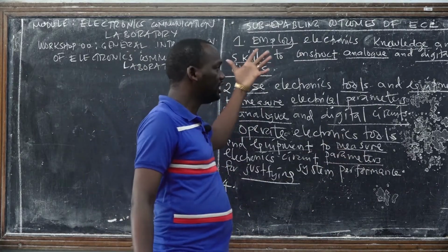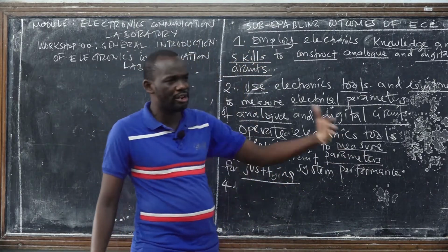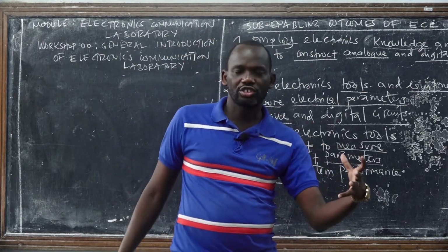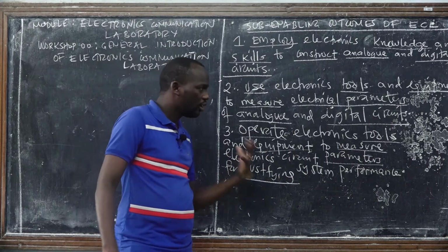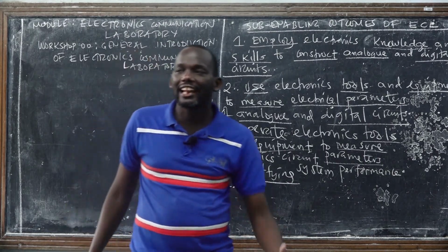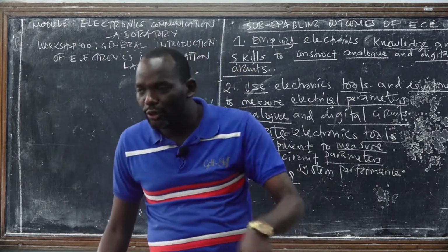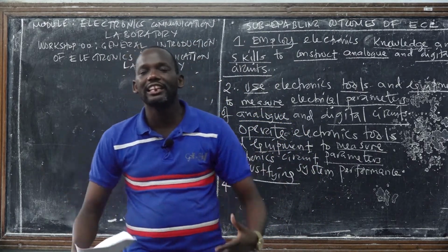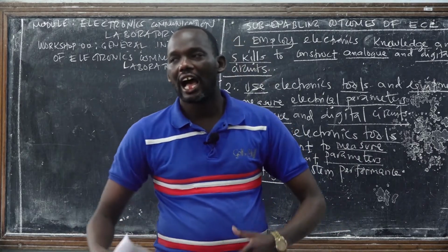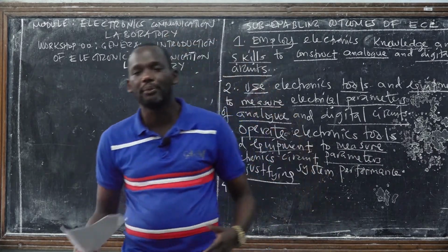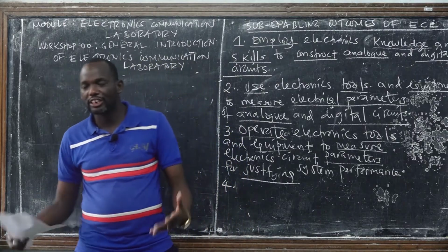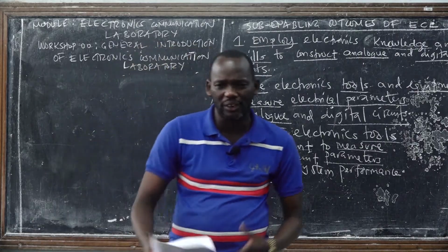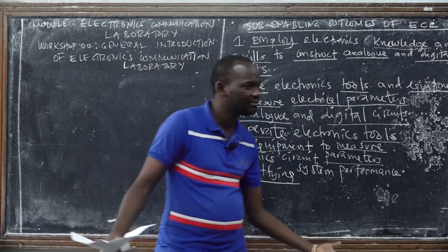So if you say the LED is turning on, yes, you have to say, okay, I have a battery of 9 volts, and I used a resistor of 220 ohms in order to limit current. So the current flowing through the circuit is a particular figure. You cannot say that the current is maybe 20 milliamperes without doing measurement. And the voltage across the LED or across the resistor, you cannot say it is 2.5 or maybe 3.5 without measurement.